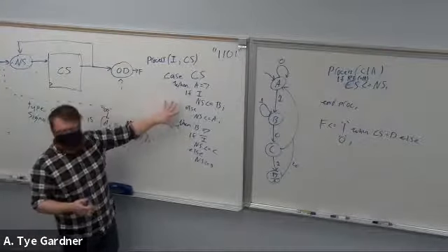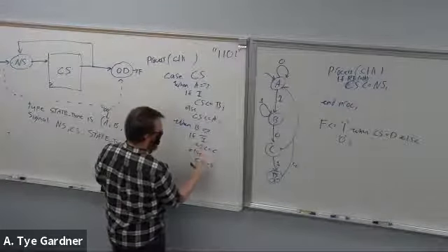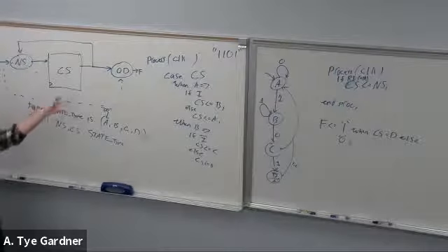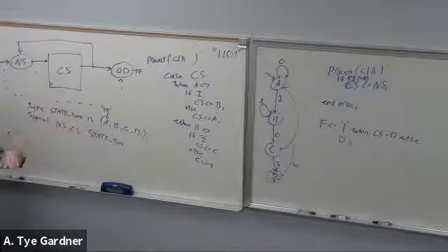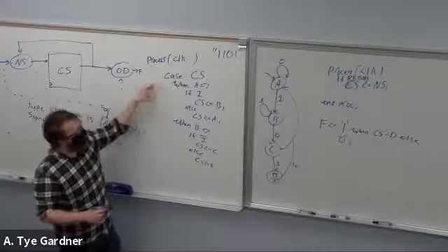if all we do is process on the clock and say things like current state. All right. Now, you have to make sure that the input I is synchronized to this state machine, right? So you don't want to have the I changing at the same time as a rising edge. But other than that potential issue, what happens is, let's say we start up.